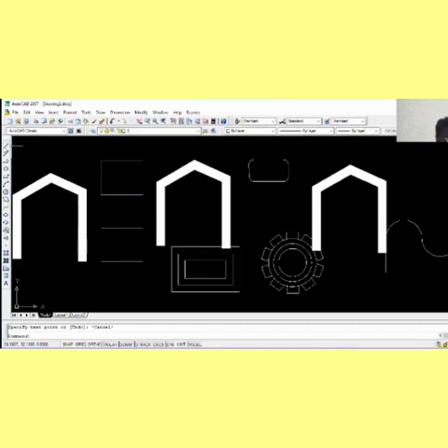So now, if you have this, let's join this to this, and then let's join this to this. Your chamfer, when you come here, you click on this. Now you have distance, polyline, undo, angle, any option you want. So now let's choose distance. You type D, enter. Now let's choose a distance of 1, enter. Second distance, 1 again, enter. Now specify the first line. You have this, and then you have this. And that is your chamfer.